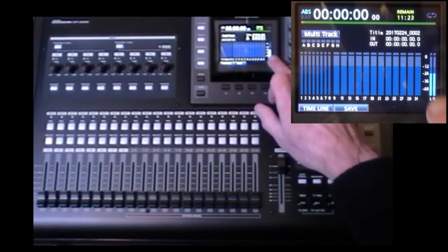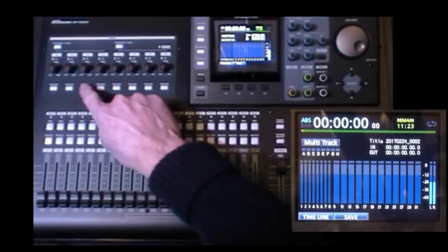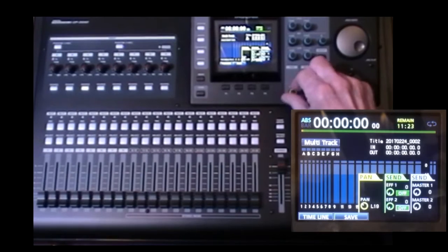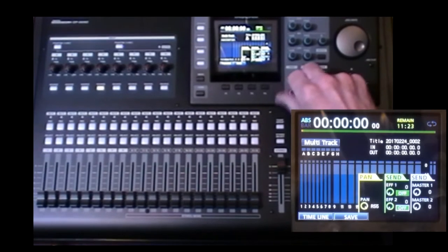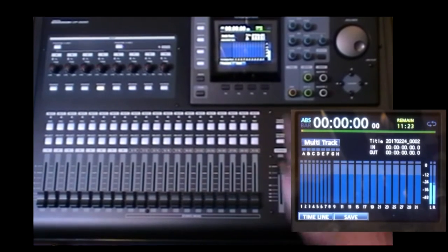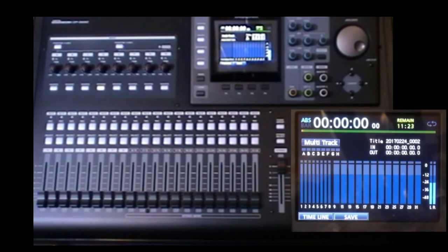You can see both left and right are going up and down in unison. So unless you alter those pan controls, the signal will be mono. So which pan controls do you use? Well, it depends on the routing, and if you route them like this, you need to use the input pan controls. So we press source C and then pan to the left, source D and pan to the right. And now you can see the levels are separate, steady tone on the left, pulse tone on the right. So the output is now a faithful stereo copy of the input.